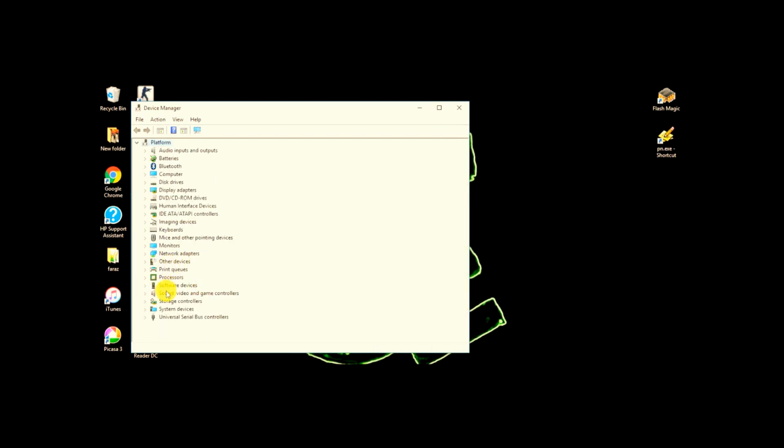Once I connect the device, the list refreshes automatically, and this device is detected as a COM port, COM5. In your laptop, it will be a different port, or it can be the same also. And this port is used for downloading the code to the microcontroller serially.